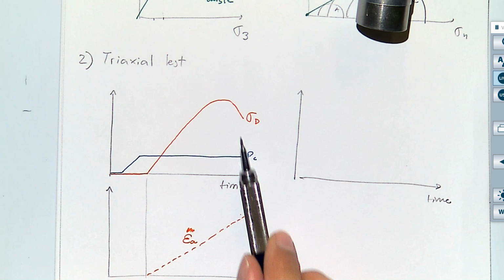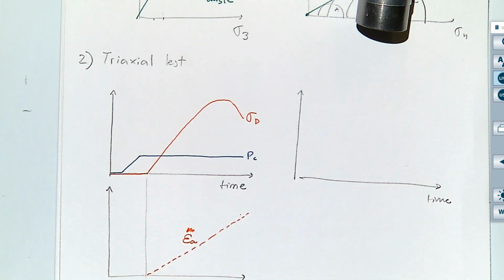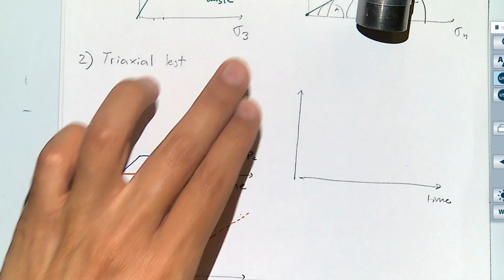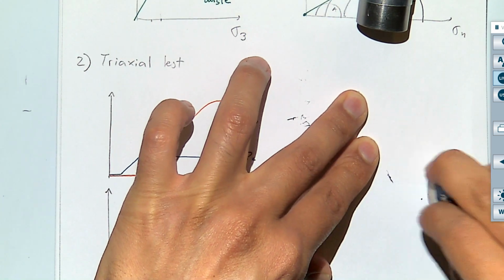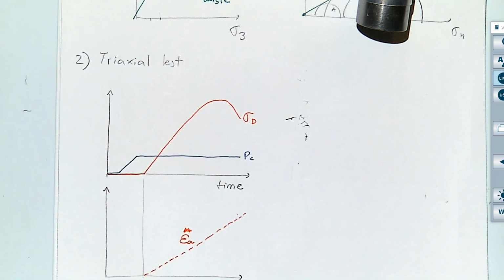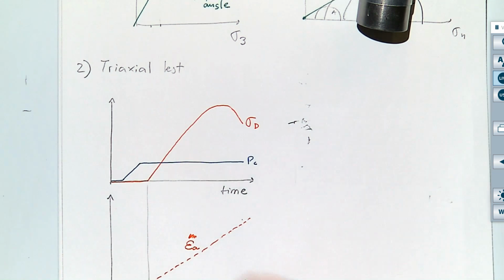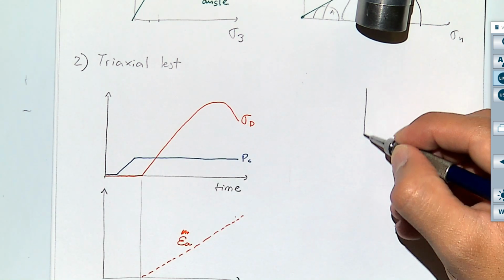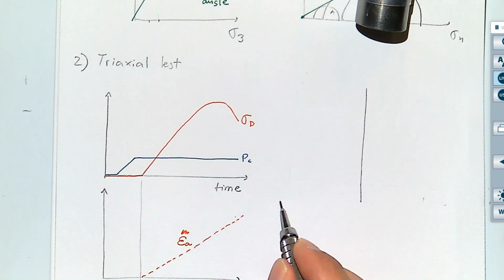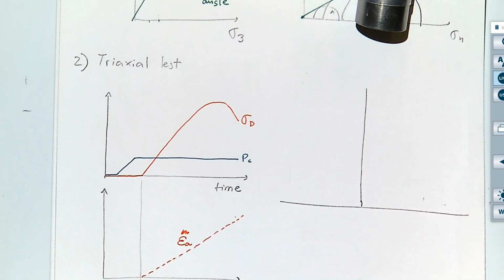And that's why you reach a maximum. All the time the rock is shortening, but then at some point it goes over a maximum, and that's when it fails. And what you're going to see from the data is that from here, you're going to be able to calculate Young's moduli and the maximum stress, and it's going to look something like this.